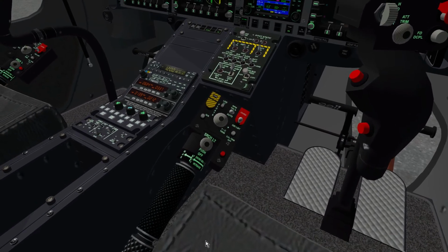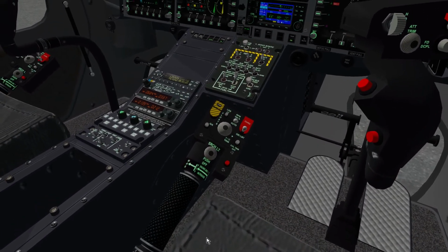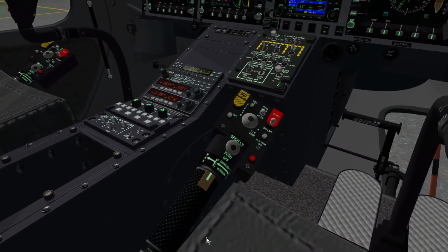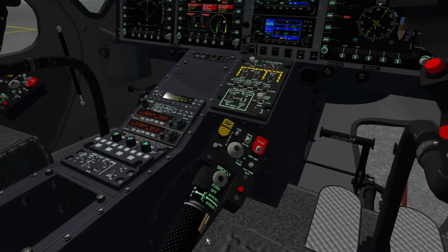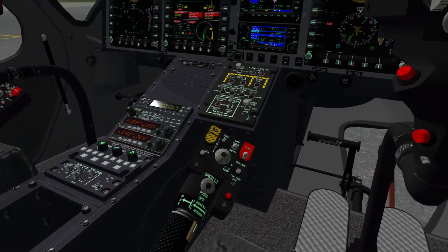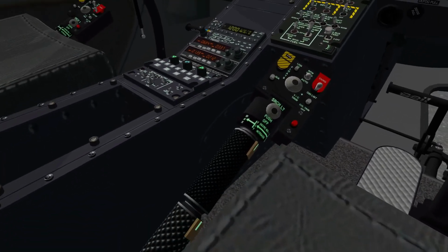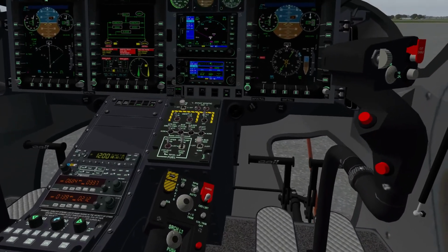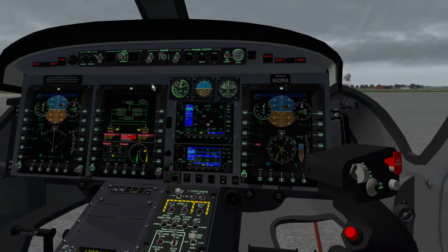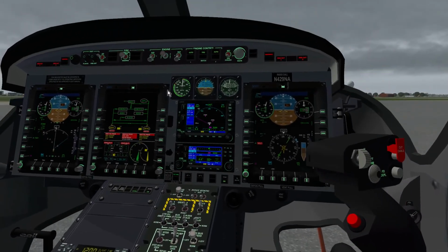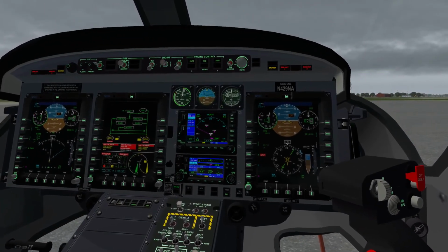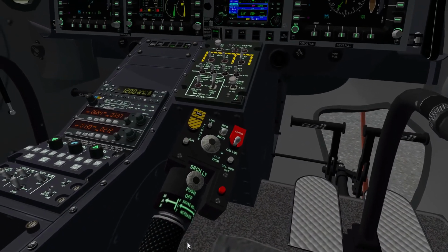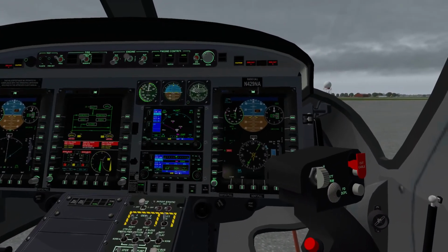Throttle control. Now I've changed the throttle so that, alright, number one, we got a flight stop and an idle stop. That would be the start position. Move number two. So we're at the idle start. To get them back closed, we have to cycle the run switches. So we will run and then off, run and off. You find the throttle's going to cut off, and we're on the bottom stop.